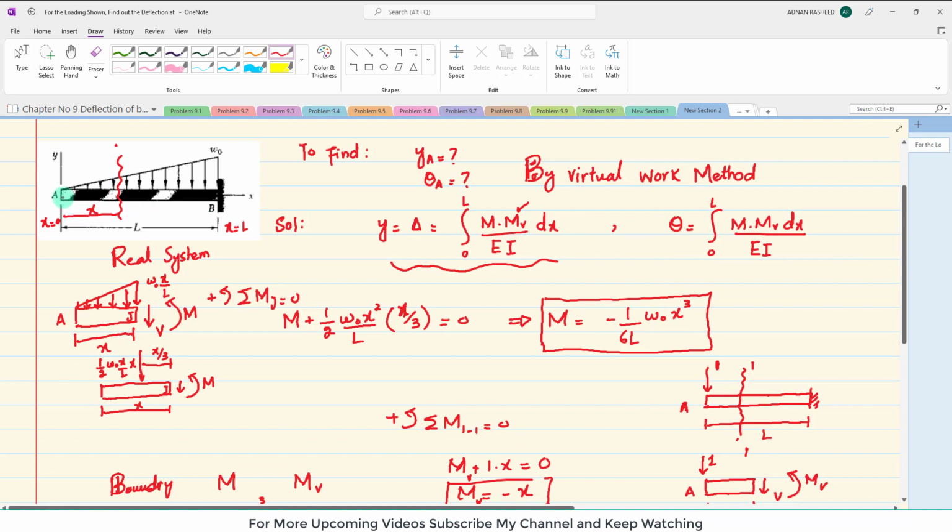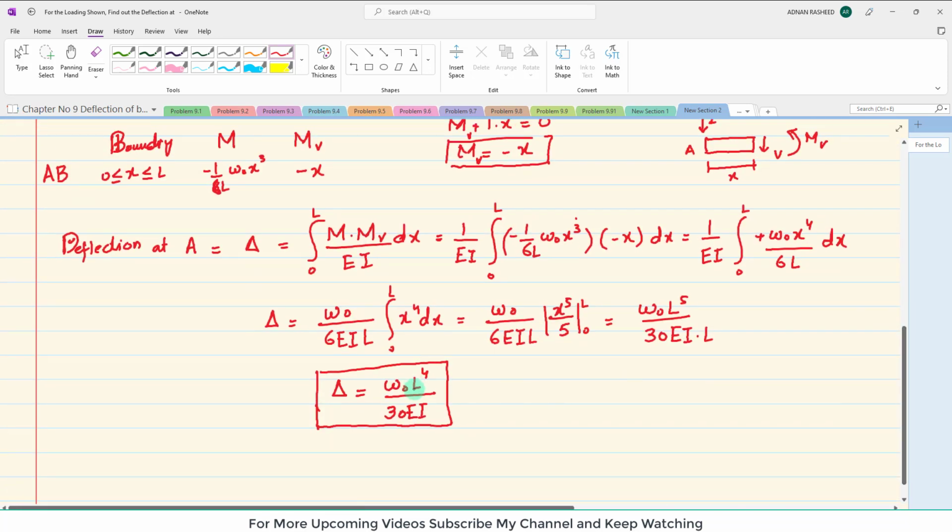Now here, this is simply a cantilever beam, so the deflection will be downward. Here this value comes out to be positive, so it means that our assumption of the direction of the force was wrong. So you can see that this will be a downward deflection. Clear? So this is the value of deflection.